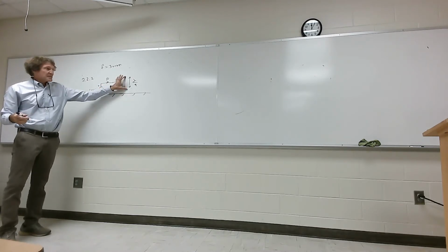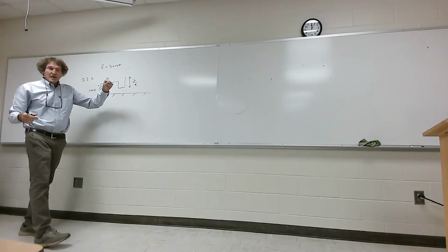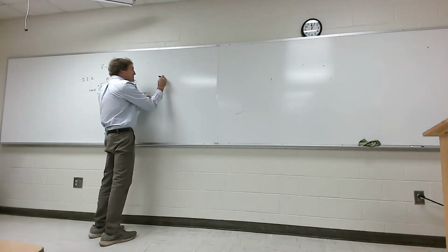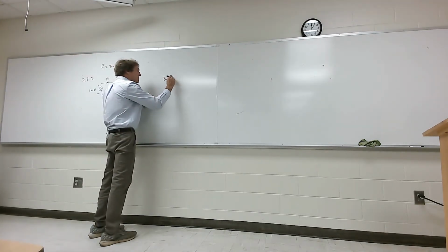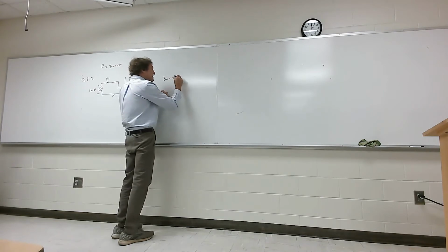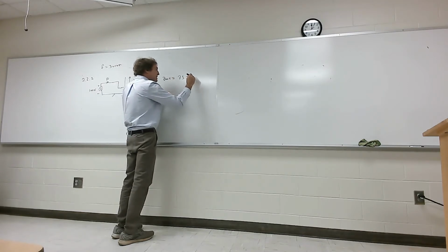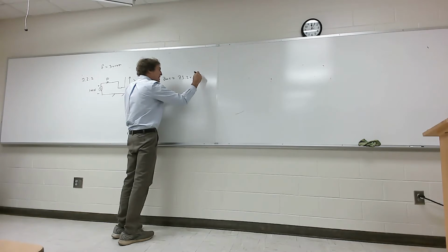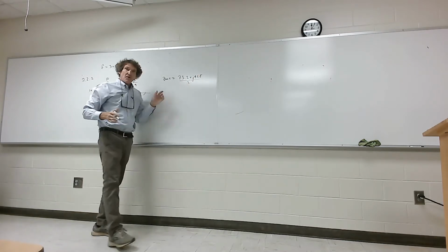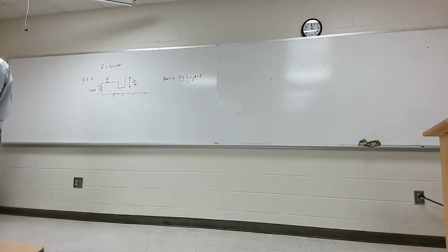So first, if that's a quarter wave monopole, you know that the Z antenna, if it's an exact quarter wave monopole, is going to be 73.2 plus J 42.5, all over 2. You all follow? Because it's a monopole, it's half the antenna impedance of a dipole. Everybody follow? Because half the power is radiated.